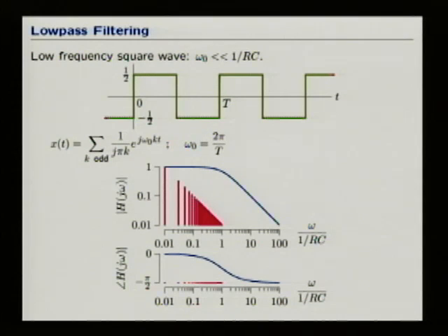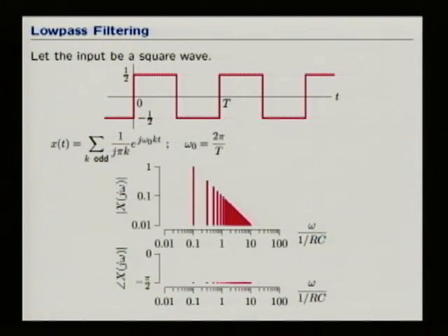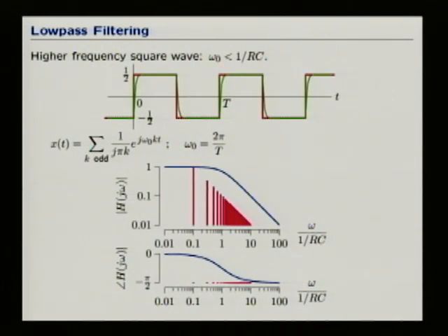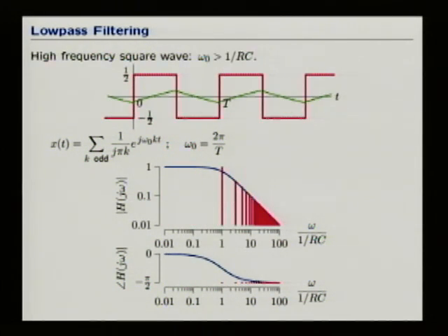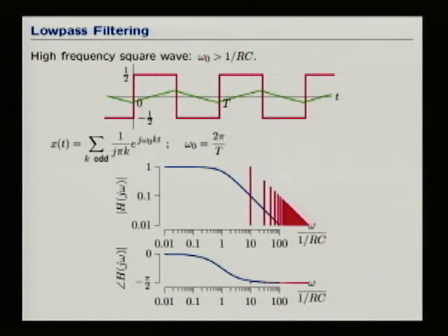So we can decompose the signal, the square wave, into a bunch of Fourier components, and then think about how they pass through the filter. If they all pass through the low-frequency part of the filter, so that the gain is 1 and the phase is 0, the output looks just like the input. And if they all pass through the part of the filter that's sloping down with a slope of -1, with a phase lagging by pi over 2, you turn a square wave into a triangle wave. That was the simplest example of a filter.